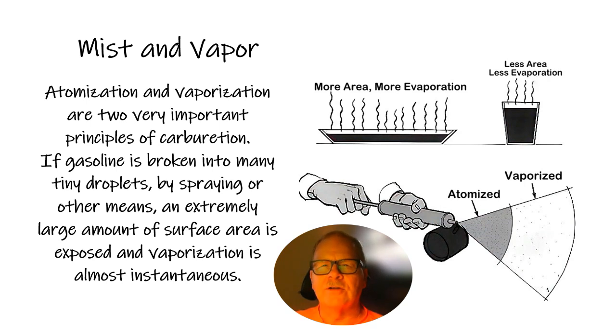You might notice that some of the carburetors that have EGR also have an early fuel evaporation feature. Some of the old Escorts had a little electric grid under the carburetor. On your General Motors cars, they would pipe the exhaust across through the intake manifold from one side to the other.